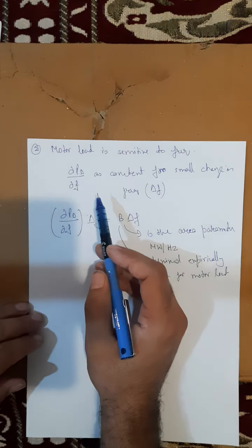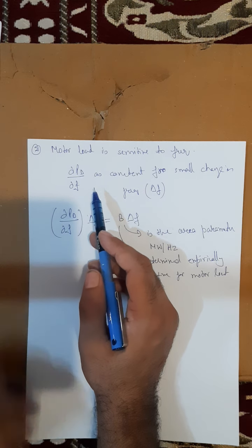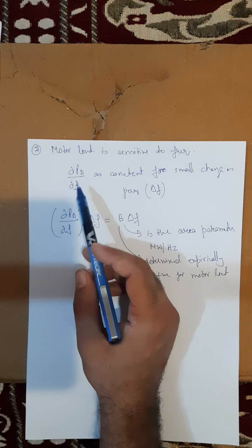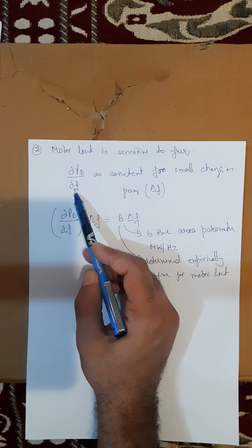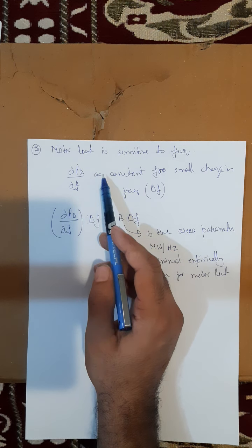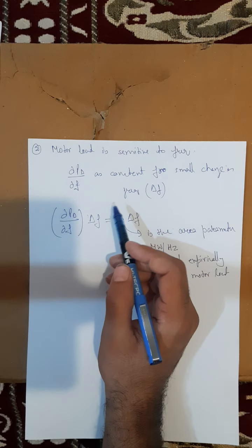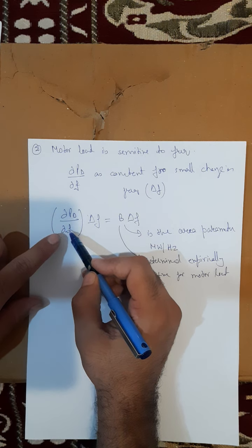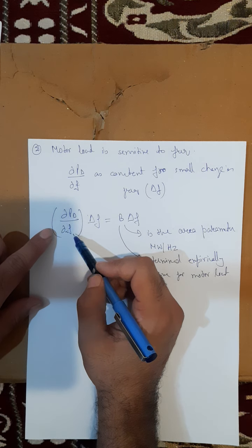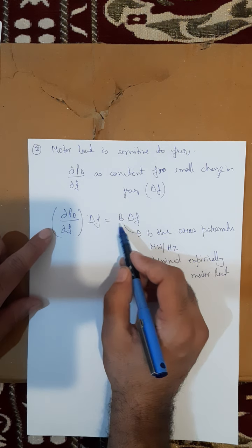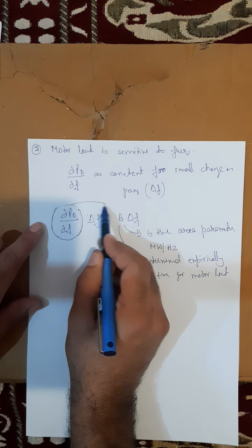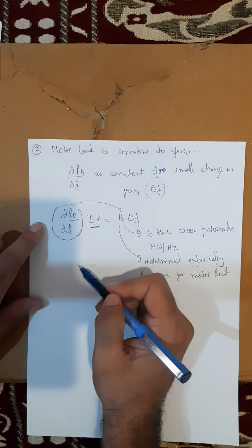The rate of change of load with respect to frequency can be regarded as nearly constant for small changes in frequency, and I am representing it by the constant B, so the change in load is B delta F.